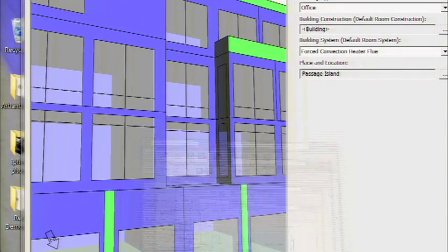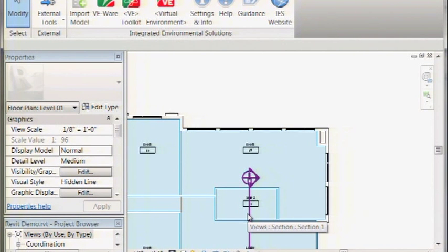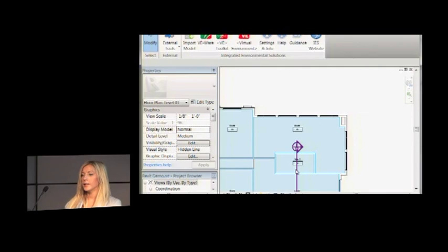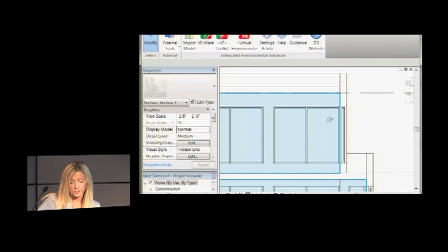dropped ceilings. As I mentioned, anything that intersects this volume will stop it. So if I have a dropped ceiling, or say I have a shelf in a room, and I made that shelf out of a floor element just because it worked well for my design, and I decided to have that stick out, if I actually go to the view, and I had a shelf coming out here, this room volume would be stopped by it.